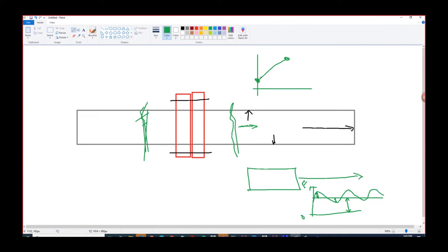This is coming from the two stress states. See, what we are providing to Sherlock is these two stresses at every node. At time 1, this is 100. At time 2, this is 300. And at time 3, it is 0.